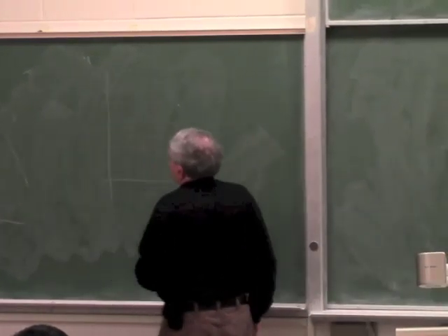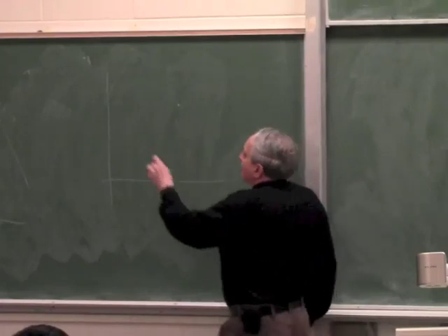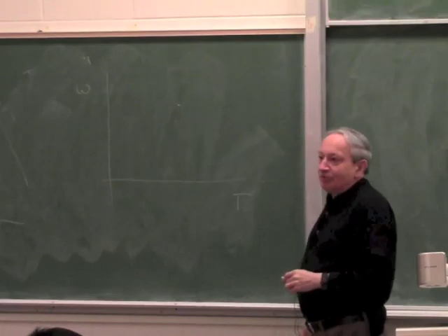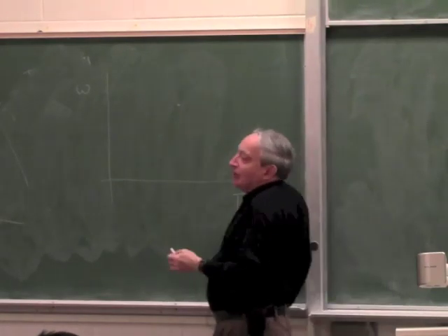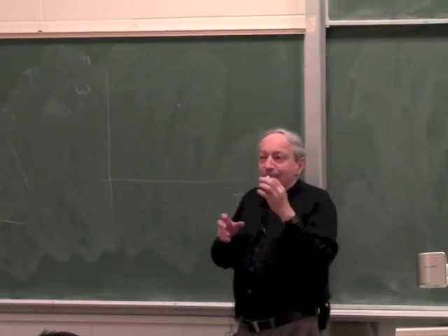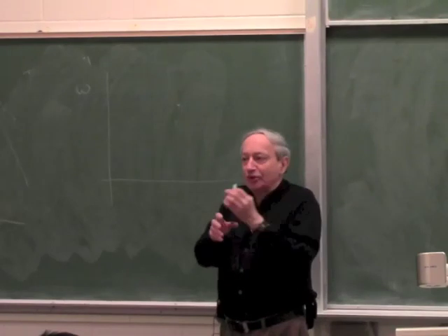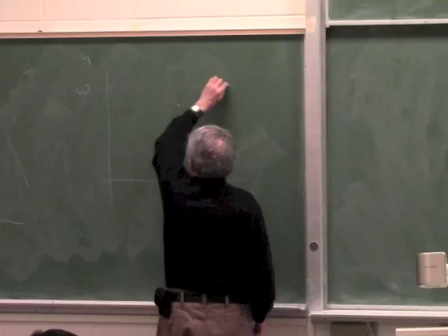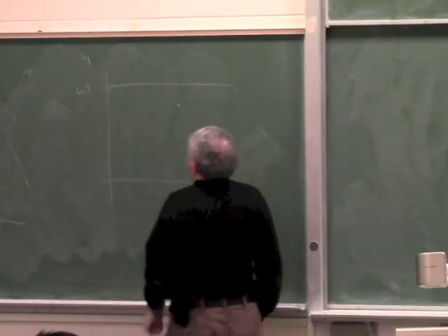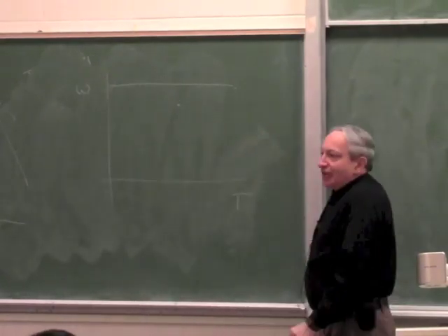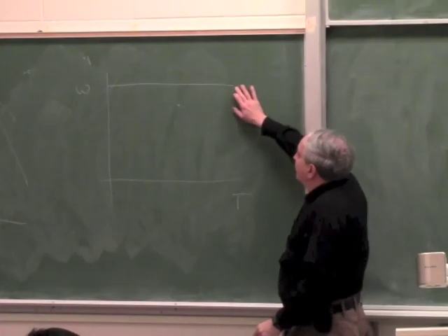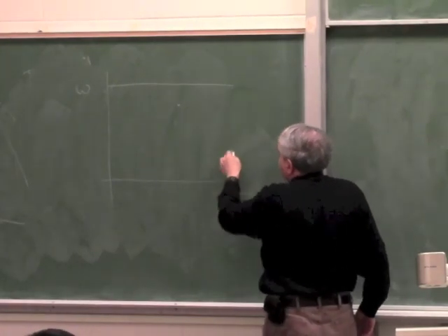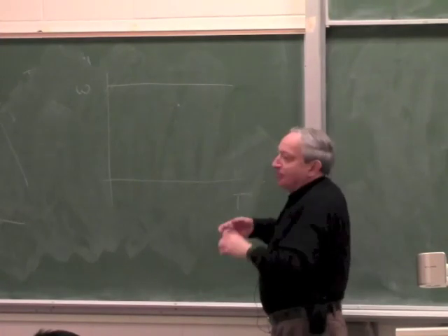Let's start with a synchronous motor. If we draw omega versus torque for a rotating field motor, since it's a rotating field where the magnet of the armature is locked to the rotating field vector, when you change the torque, the speed doesn't change. Now, simplistically, you tend to draw it like this, that at a certain torque it breaks lock.